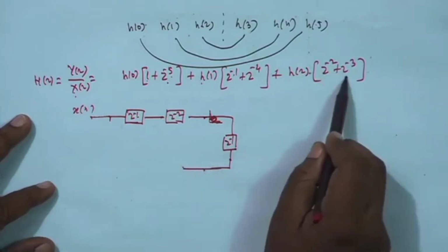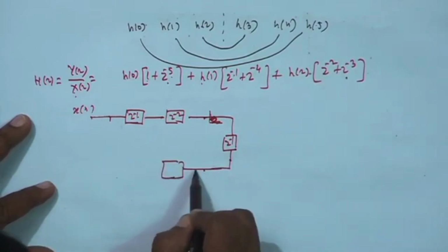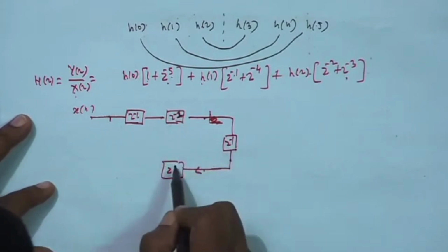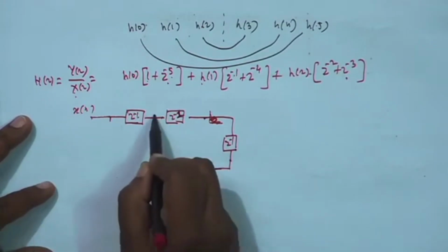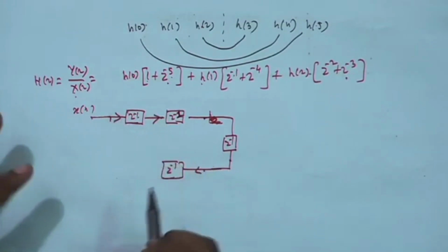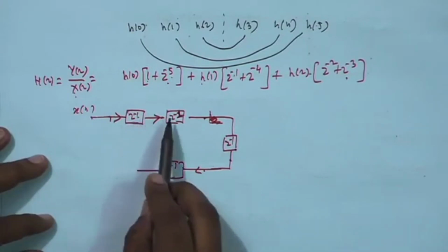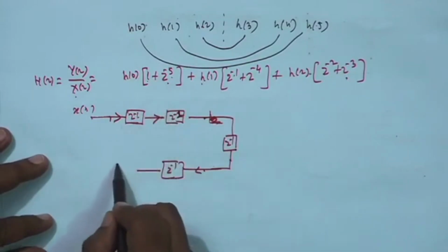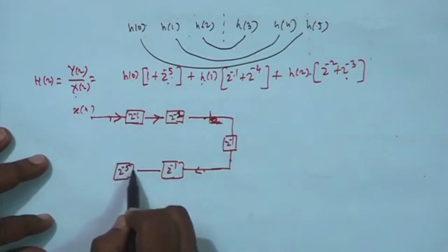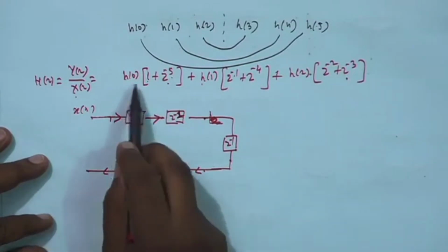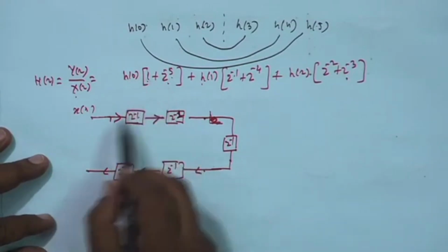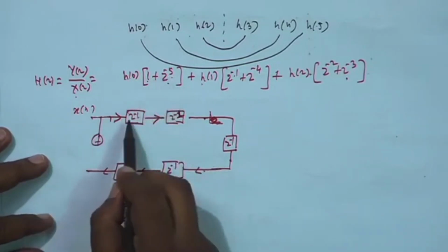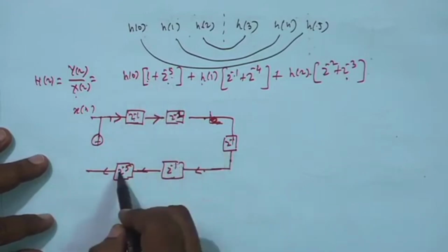Then, there are Z inverse 1s. So, Z inverse 4, up to that I have reached, but I need Z inverse 5 also. So, one more delay. So, X(z) into 1 plus Z inverse 5. So, x[n] plus x[n minus 5], n minus 1, n minus 2, n minus 3, n minus 4, n minus 5. So, from here you take